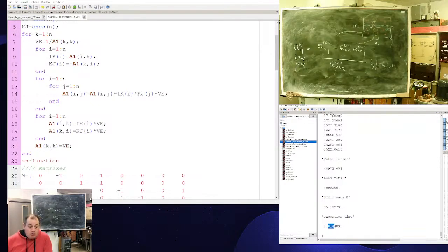So now we see how we can solve a DC network with constant power or any controllable load. Just substitute the simple current as power divided by voltage with some kind of feasible representation of the load strategy, as a current that should be given as a function of voltage, and it will work. You will get a result. None of the electrotechnics theory books tell about this.